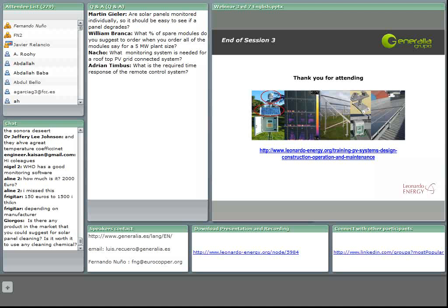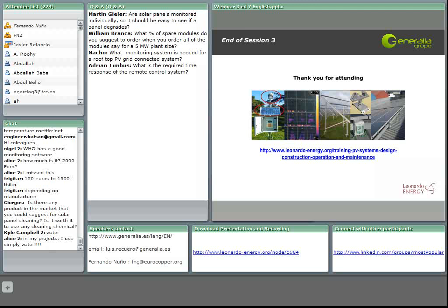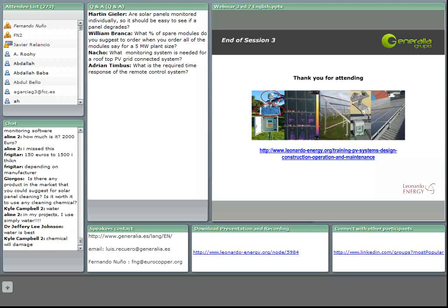For example, if we have detected that the position of a sun tracker is not synchronized with the position of the sun, because we are detecting that the energy produced in that sun tracker is lower than the energy being produced in the rest of the sun trackers in the PV facility, it is important to be able to modify in real time the data for that sun tracker and modify the position. For example, if you get back, Fernando,